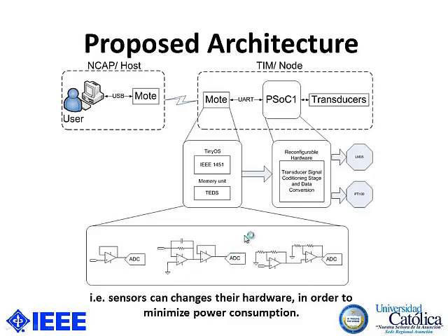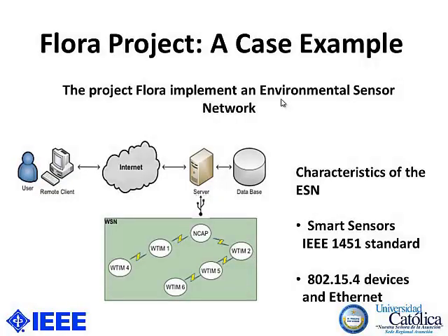And we use a PSoC 1 device. This is limited to 8 different preloaded configurations. So you can do one configuration, for example, for all digital sensors, another for all analog sensors, or another for mixed sensors, and you can change between configurations on the fly, very fast.